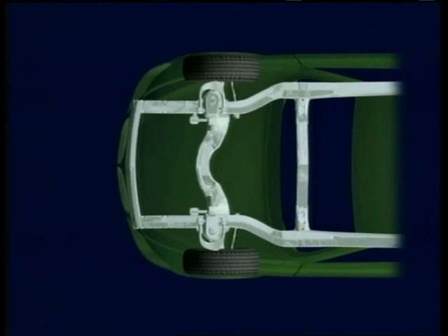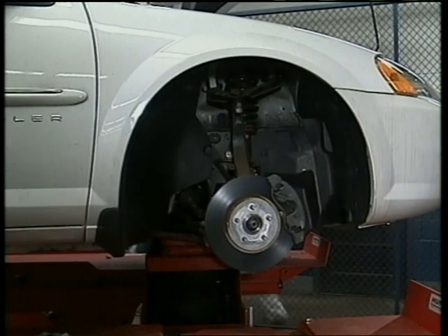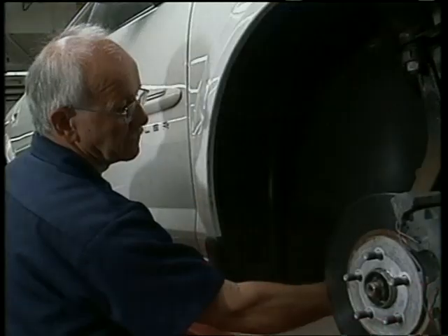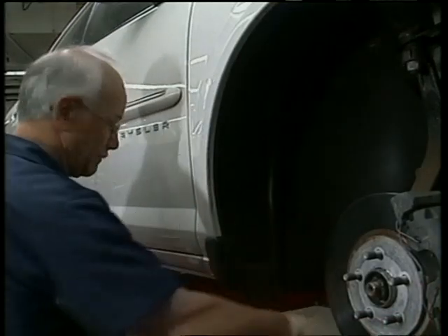This slight toe-in compensates for play in the steering system and suspension action. The tires on rear-wheel drive vehicles tend to toe out while driving, and the small amount of toe-in adjustment will cause them to roll straight. Front-wheel drive vehicles need to have their front wheels set for dead ahead or with very slight toe out. The front wheels can be forced inward by a drivetrain torque on a front-wheel drive car. A very slight toe out will keep them straight while driving.